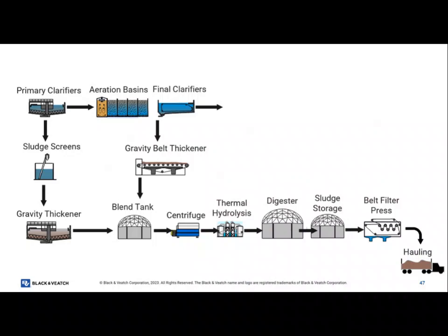The big thing that happened here was VFAs coming in. We're normally in the probably 60 to 70 milligrams per liter. That's normal coming into their selector. Steve, what were they coming in at? We were over 100? Yeah, so essentially all that extra VFA, they were normally in the 60 to 70, they had 100. All that VFA would normally get sucked up in here. What started happening was VFAs were bleeding into this zone here.